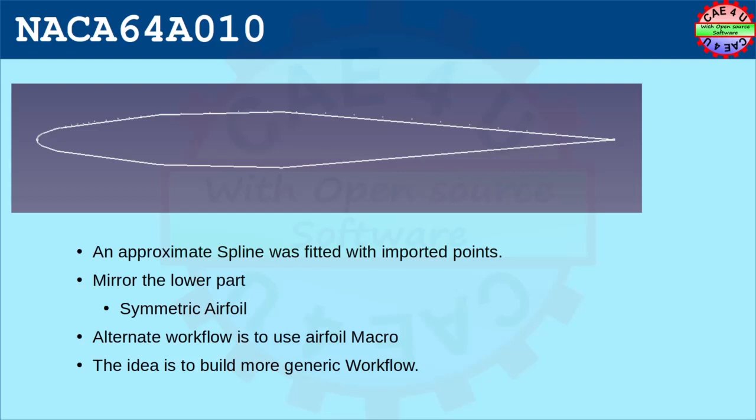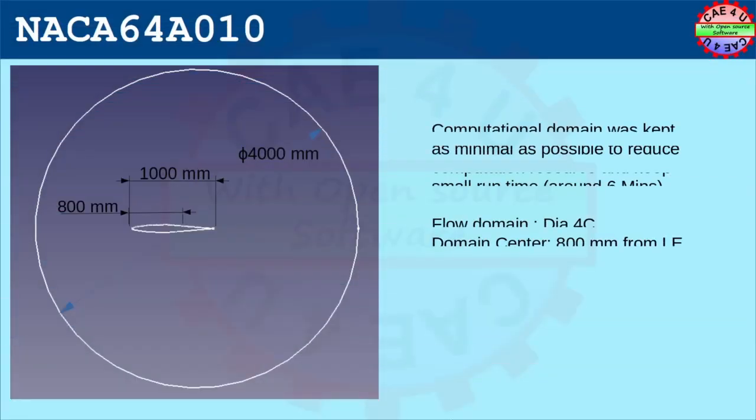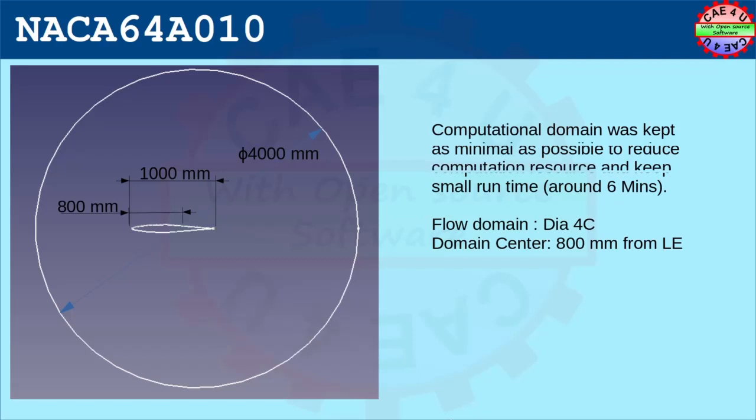An important consideration is the computational domain itself. There are many shapes to define the computational domain, for example, the D type, O type and so on. We opted for the O type just for ease of use. The size consideration of the domain is important because the far field zone should be a true far field.